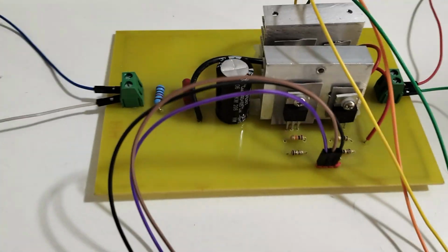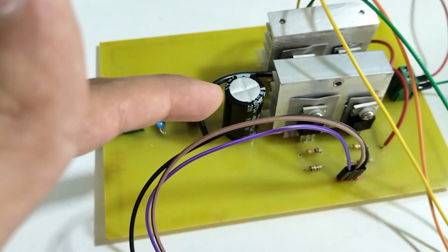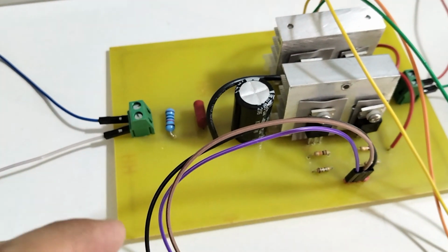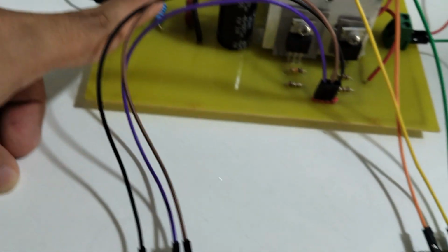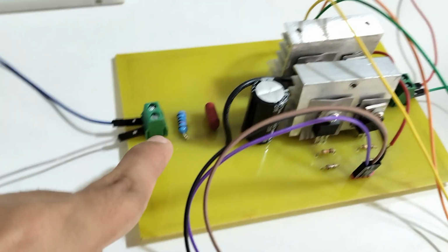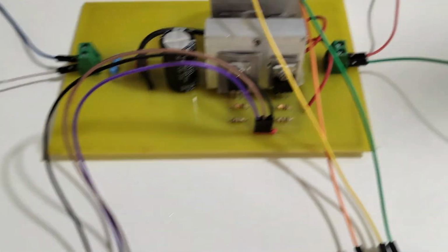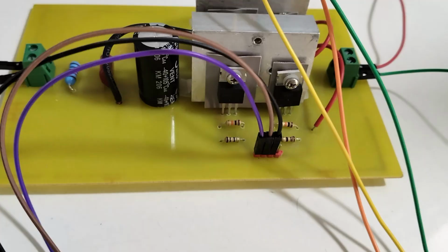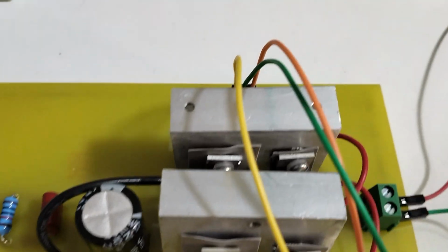So other than that, in the H-bridge PCB, we have the DC bus capacitor. It's 2200 microfarad, with another 100 nanofarad in parallel with that, just for high frequency noise. And that's a bleeder resistor, which makes sure that your capacitor discharges after you turn off your circuit. And those are the actual four MOSFETs. We have one leg here, and another leg is here, two MOSFETs.